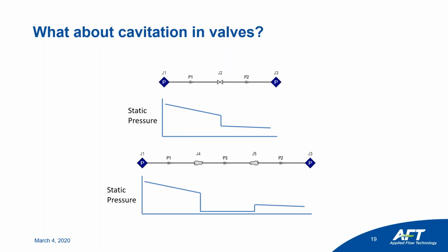Note if you spot cavitation in a valve in your system, or if you believe there might be, this is something to consider, but in no way will Fathom really indicate it to you unless you're cavitating at the outlet of the valve. Then it'll be an issue because you'd be cavitating in essentially this entire pipe. So that's cavitation in valves. Cavitation in general, looking at NPSHA, NPSHR. Again, how do we look at the system instead of just looking at the problem area of the pump itself?